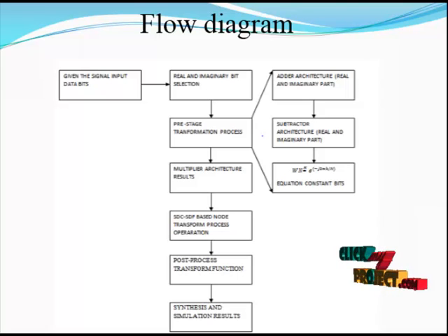The multiplier requirement is approximate. The proposed design preserves the Radix-2 nature and achieves 100% multiplier utilization, while the other Radix-2 designs only achieve 50% utilization. Furthermore, the high Radix designs require more complex adders than the proposed design and can only process FFTs whose size is a power of its high Radix. The 128-point FFT cannot be directly mapped to either high Radix design, but the Radix-2 design can. Beyond the scope of this brief, the mixed Radix design can implement the 128-point FFT with relatively complex control logic.